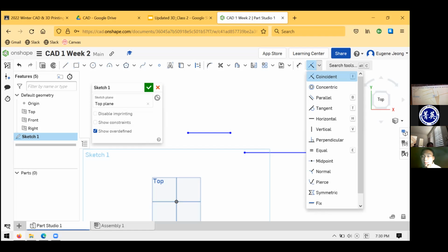Why is it yellow now? It's either because you have everything selected or there's an error, but I just click the sketch button and it. Oh, wait, that just means you had it selected. To edit the sketch, remember you need to right click it and hit edit.